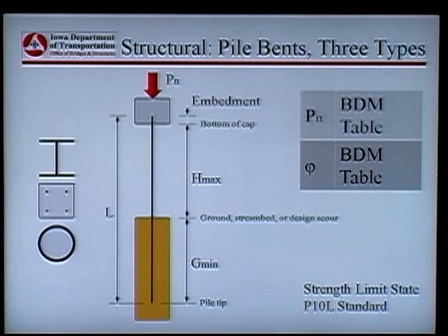In the case where we have pre-designed pile bents, we set up the P10L sheet, which used to be a P10A. We've set that up so that you can just design for a vertical load. We've set the limits and everything so it covers an ordinary amount of moment and so forth in the pile. We've set that up for the H-pile, pre-stressed, and pipe piles.